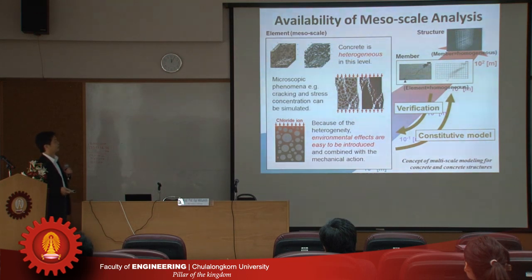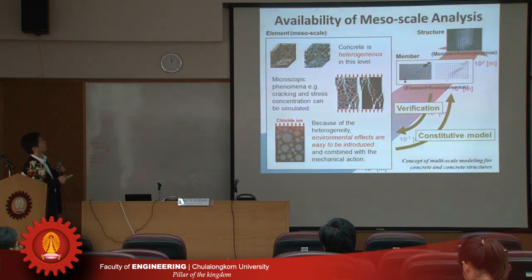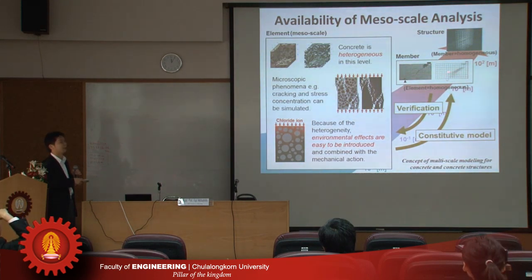In this slide, I want to explain the concept of mesoscale analysis, but maybe you already know it from the presentation by Dr. Sato. The definition of mesoscale analysis is that the target size is a bit smaller than the member size of the concrete structure. In member size, we often conduct FEM analysis, right? In this FEM analysis, the constitutive law of the concrete is a stress-strain relationship of one element of concrete.